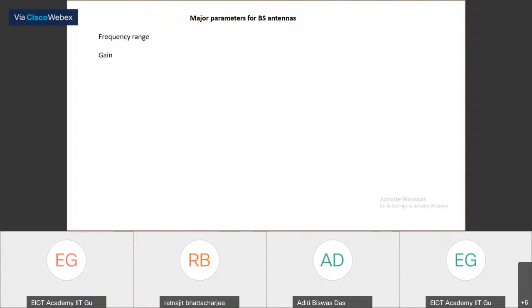If it is a metallic antenna, it will dissipate some power. The metal will have finite resistivity, and you will not get all the power that is given as input to the antenna as radiated power. And therefore, we talk of another term which is called the radiation efficiency.